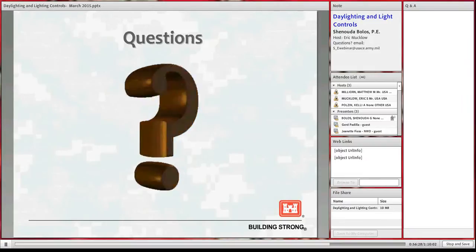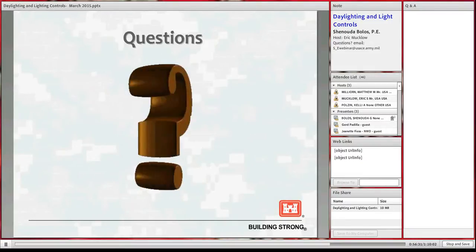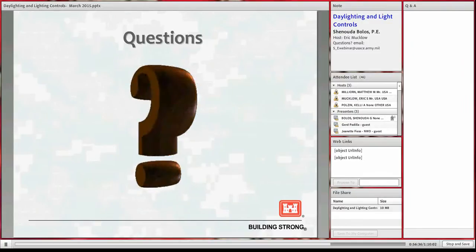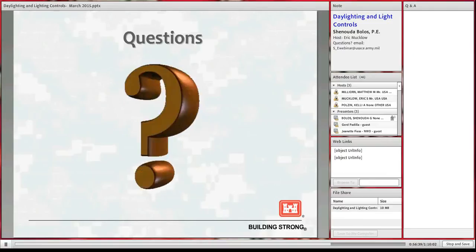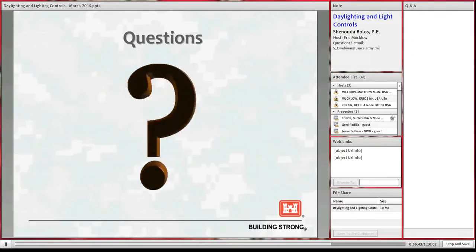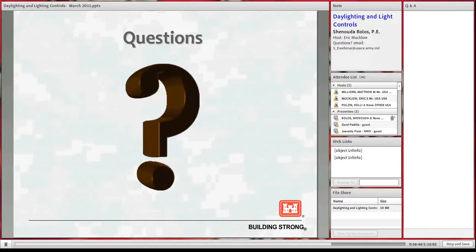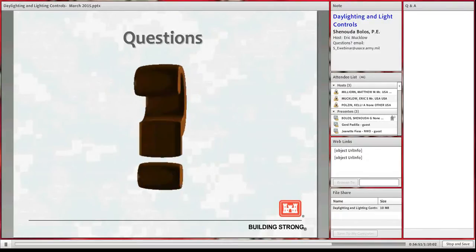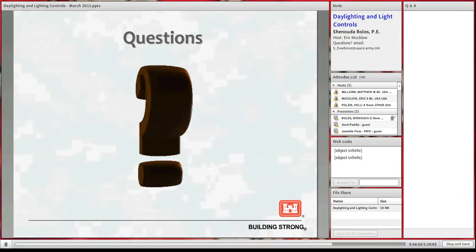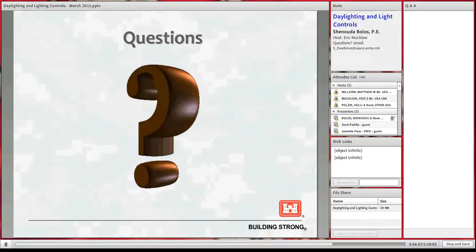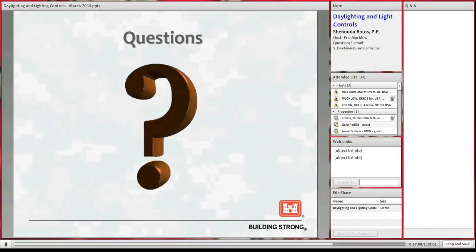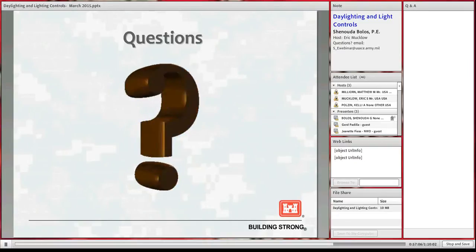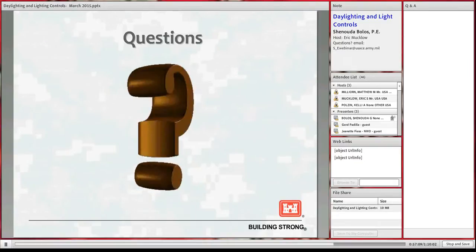Back to the two topics we talked about, daylighting and light controls. For daylighting, there are maintenance requirements for something like a skylight, as well as cleaning the windows and skylights. Back to the type of manufacturers, the standard doesn't specifically say how much maintenance is required for the daylighting methods. It goes specific by each manufacturer for the other mechanical ones, which are the shades and solar shading. It depends on the manufacturer and the type you recommend.